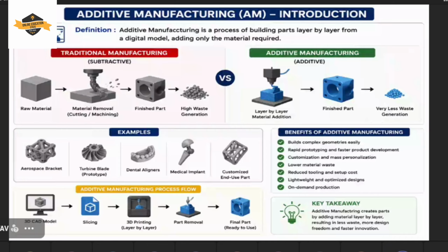While if the same part is to be produced by additive manufacturing, the extruder will deposit material only where it is desired. If there is a hole, material will not be deposited in the hole. We can optimize this path of design, this entire formula of production, and we can generate it in computer software. While slicing the models, we can optimize all these parameters so that zero or very little waste is generated, because the material is deposited only where it is desired as per the design.